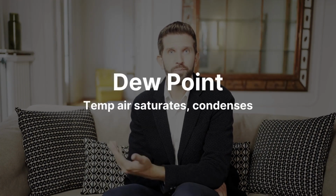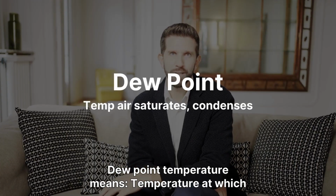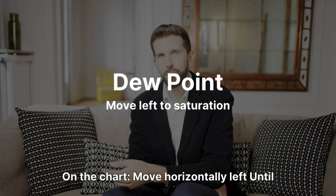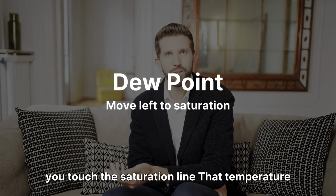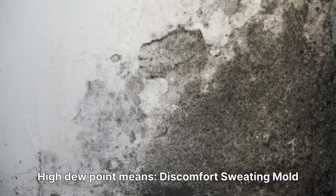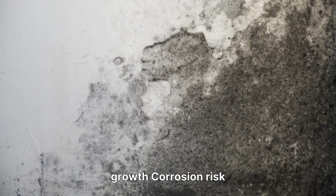Now dew point. Dew point temperature means the temperature at which air becomes fully saturated and water starts condensing. On the chart, move horizontally left until you touch the saturation line. That temperature is the dew point. High dew point means discomfort, sweating, mold growth, and corrosion risk.